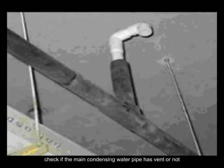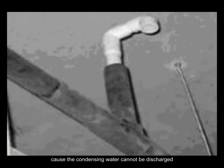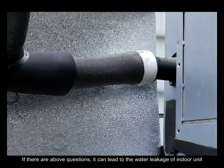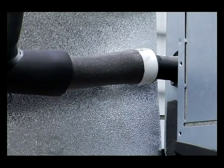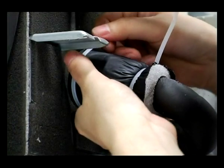Check if the main condensing water pipe has a vent or not. Check whether the main discharge water pipe is jammed, which causes the condensing water to not be discharged. If there are any of the above problems, it can lead to water leakage of the indoor unit. Please modify it according to the requirements of the technical manual.